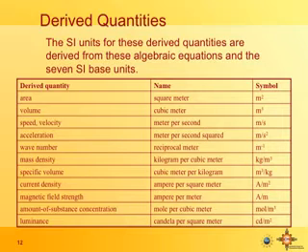You can push more water through a bigger pipe. Magnetic field strength is ampere per meter. Now that's kind of a strange unit, and when you work with magnetic systems and magnetic sensors, it becomes important to characterize your sensor as to what it can actually detect. Maybe your sensor puts out a voltage that's proportional to the amount of magnetic field it senses. So you would have to do a calculation to compare the magnetic field strength to the voltage output of your sensor. That way your customer who's buying your magnetic sensor would be able to tell how sensitive your system is and if it will work for his application.